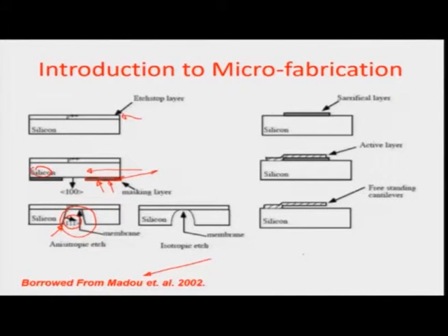But whatever it is, without getting into those details of chemical etching, I can say that the masking layer was present and later on you pull out the masking layer, you see there is no masking layer here. So, you dissolve this layer in a suitable solvent, but until it was present, the chemical did not affect the regions where the masking layer was shielding. Okay. So, this is a very important essence.